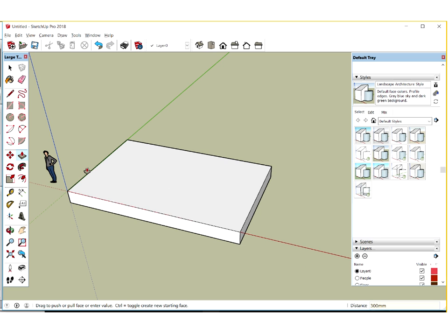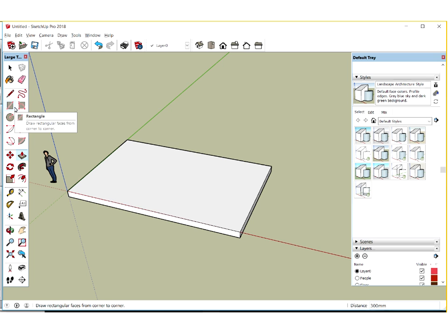So, Nikki, I'll give you a second to do that one, and then put up a green tick once you've done that. So it's just the rectangle tool, click on the junction of the 3 axes there, drag in the direction that you want, then type in the dimension, always hit enter to finish your commands. We'll give it some thickness. We'll talk about the importance of grouping, things like layers as well. Alright, good work. Give it some thickness as shown as well.